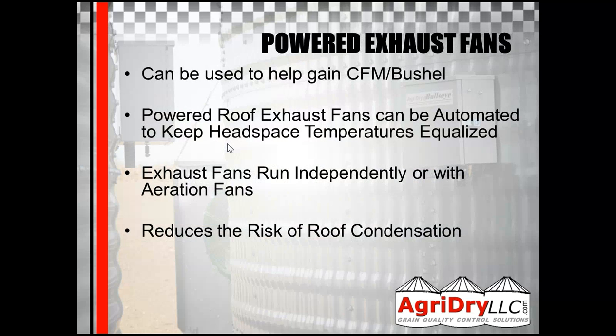Another way to capture that is not only just roof vents by themselves, but powered roof exhausters, to help pull that air out and exhaust that air out. A lot of larger bins, whether it's large farm bins or even large commercial bins, use powered roof exhausters. And obviously that can help with your CFM per bushel as well, because you're helping pull that air out of the top and circulate that air, which then cuts down your static pressure. They can be automated to help.